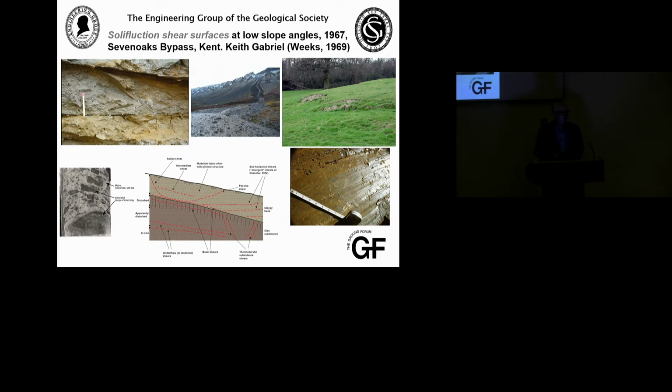So this was a site which was characterized by the process of solifluction, the legacy of solifluction. And so we took our glacial specialist and our periglacial specialist from their quaternary environment, and we said, come and look at our magnificent solifluction site. And they said, that's not solifluction. They're active layer detachment slides. They're full of shear surfaces. Why would you have shear surfaces in something that's moved as a liquid, rather than something that's moved as a supersaturated mass?